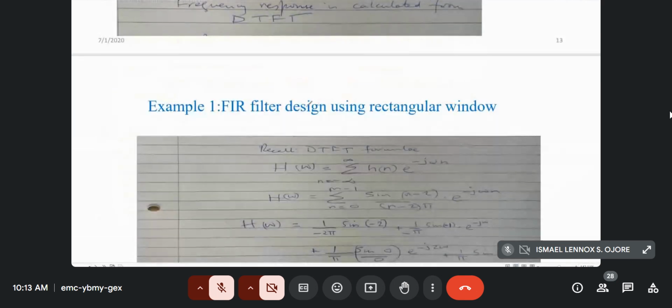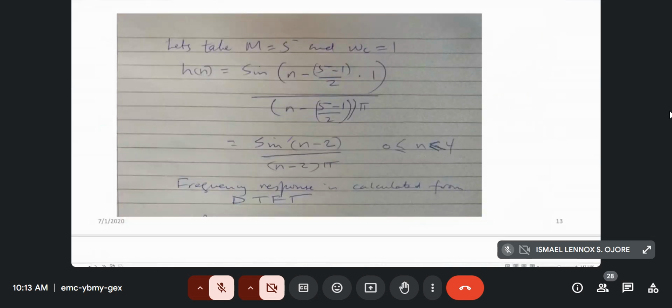So now we can work out the DTFT. Actually, what we have done here, we have not even calculated it. It depends on what your question was. Our question here was to get the frequency response. But if you are just being asked to get your h[n] sequence, then what you have done is simply replace this from 0 to 4.